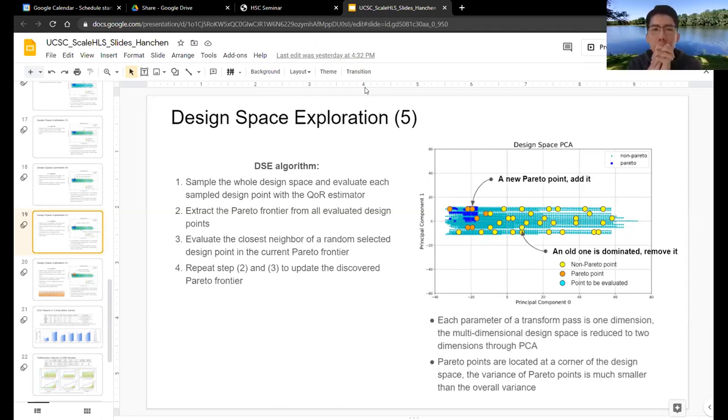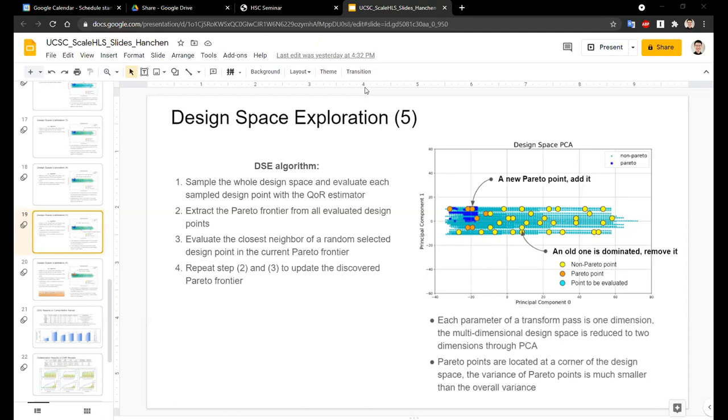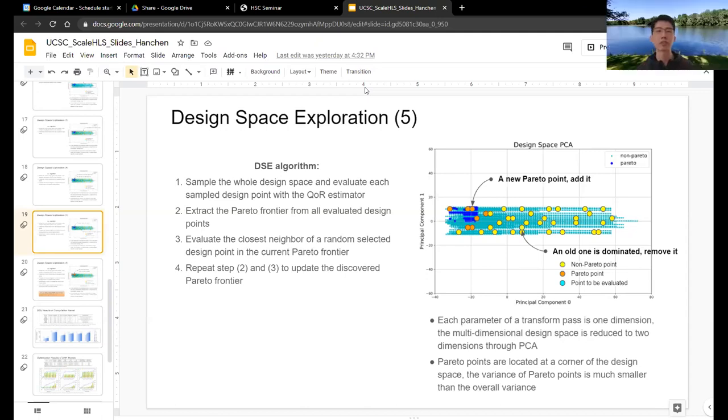Oh, actually, it's a problem of comparing the functionality of the baseline C code and the emitted C++ code, right? So yes, I think you can. I think the easiest way is to use the traditional method. You write testbenches to call the baseline C code and the optimized C++ code, and then you can verify that they have the same functionality.